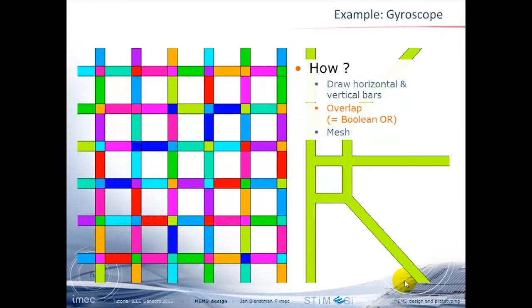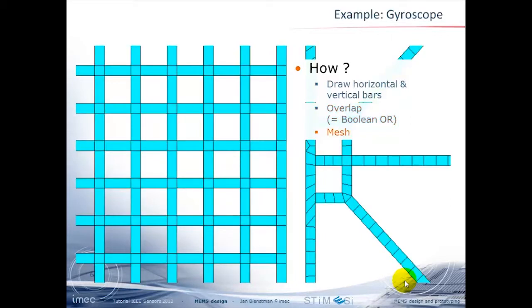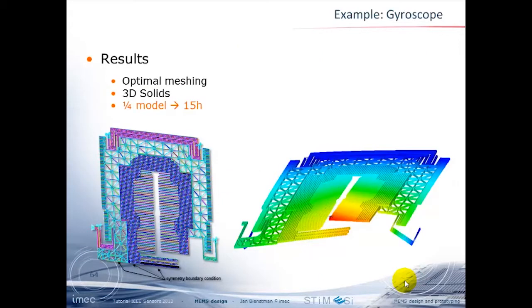And then for example, if this width was 2 microns and that was, let's say, 6 microns, then I mesh with a mesh length of 2. So actually every region is translated then into a mesh element. And a very regular mesh. Just a stupid trick to fix and to control or get my hands on how the mesher will create a certain mesh. And then it worked.